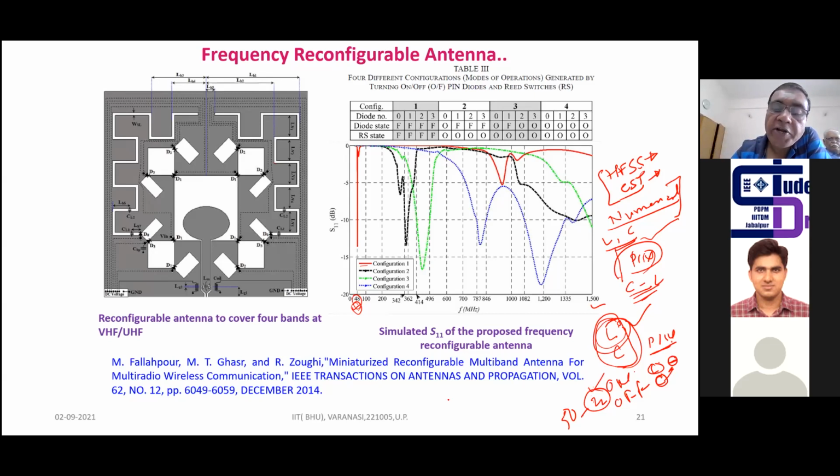One thing is that when you are using numerical software, in each and every numerical software there is a criterion called the stability criteria. Do you know about this one? No, sir. So when you are running any simulation software, not only CST or HFSS, any simulation software based on a numerical technique, you must check the stability criteria. Each and every numerical technique has some specific stability criteria.